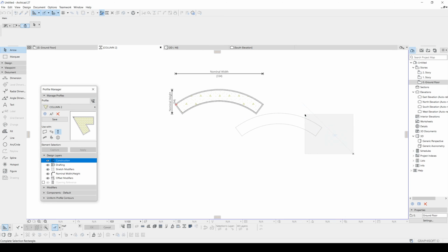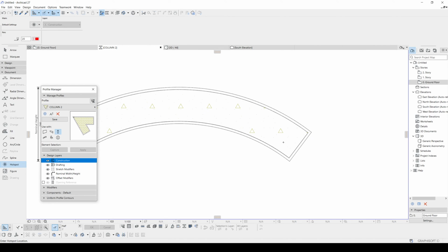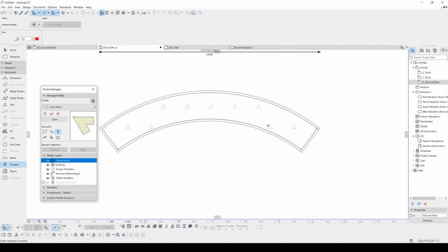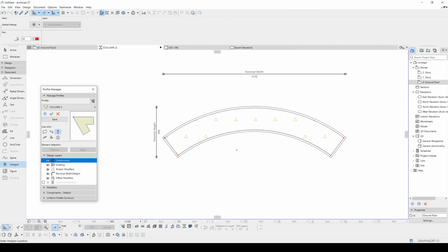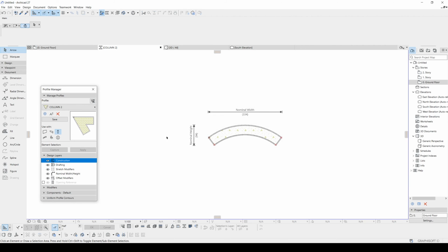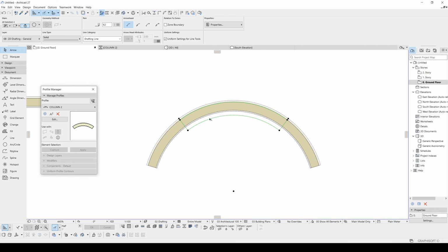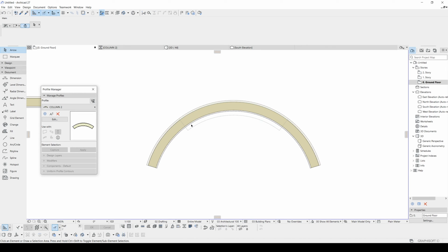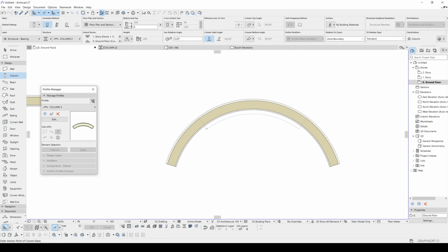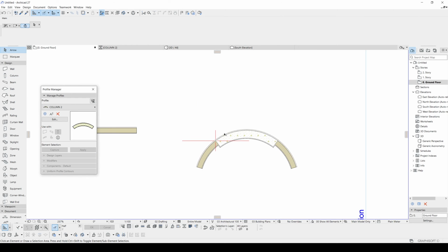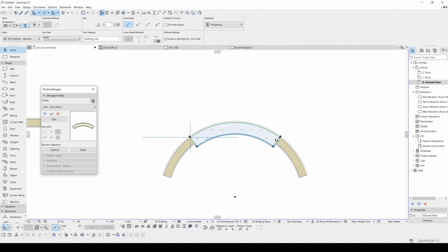and it's nearly ready. We need to place our hotspots. It's important because when you are dimensioning, your dimensions will stick to these corners. Otherwise, your dimension cannot stick to your corner and flies on your model. Alright, let's hit the save, and I want to delete this because I'm going to use this as reference. Let's go to design, column, and column 2. Let's just delete the inner lines.